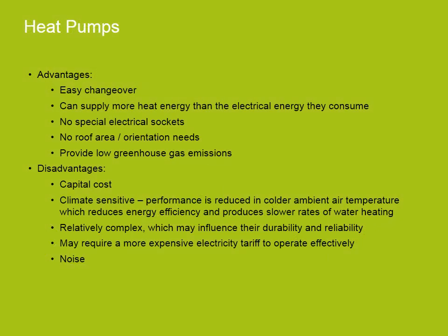Some advantages of heat pumps are their easy changeover installation. There is no need for special electrical sockets or roof or orientation space needs. It can supply more heat energy than the electrical energy that it actually consumes and has very low greenhouse gas emissions. Some disadvantages include its high capital and installation costs. Heat pumps are climate sensitive, meaning that their performance is reduced in colder ambient air temperatures, which reduces energy efficiency and produces slower rates of water heating. Their systems can be relatively complex, which may influence their durability and reliability as customers may not know how they work. They also may require a more expensive electricity tariff to operate effectively. Heat pumps can also be noisy.